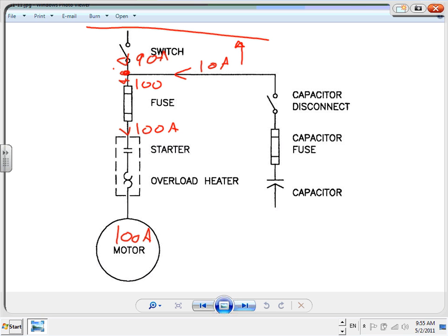So I corrected, every time this 100 amp motor comes in, I corrected the power factor for it. What's the issue with this though? If this is on, this will be on. What if I turn this off? What's going to happen to the capacitor? Still on. The capacitor is still on. So this could get you guys in a situation where you have over voltage, over correction.